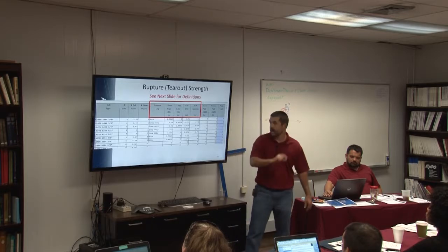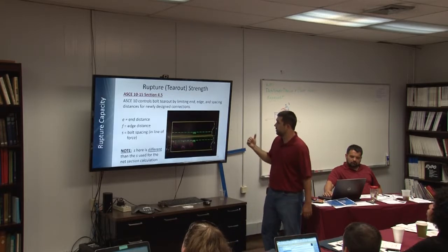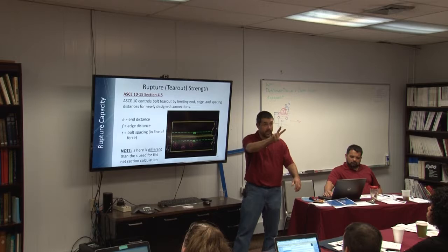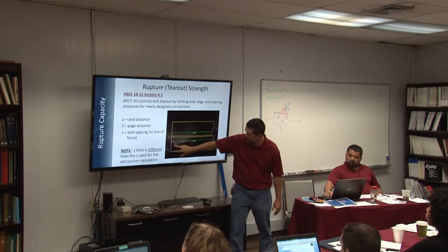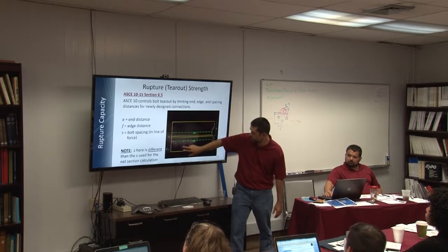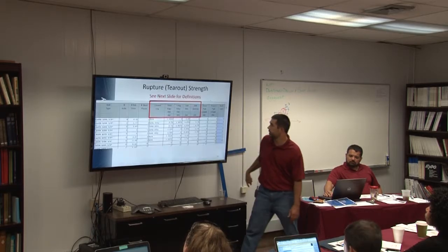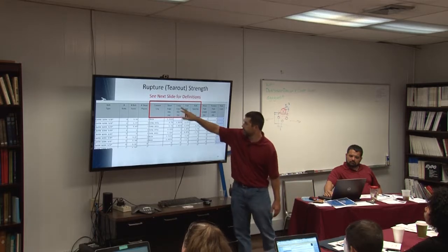And then the edge distance, they actually, can you go back one slide? So you actually can define two gauge lines. You can define the edge distance of the closest hole and the second closest hole. So this is called the short edge distance, and this is called the long edge distance. So you can go to the next slide. So you can put in short and long.